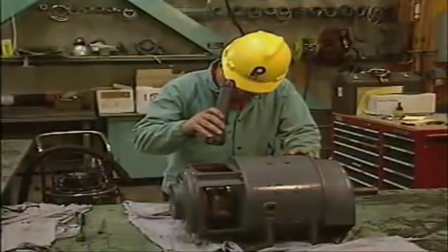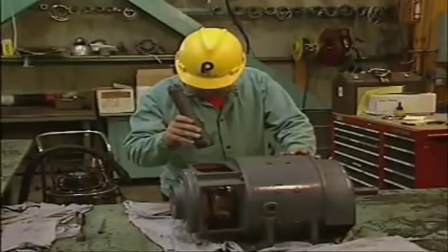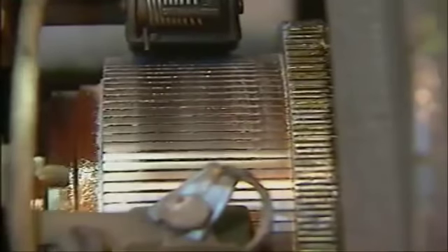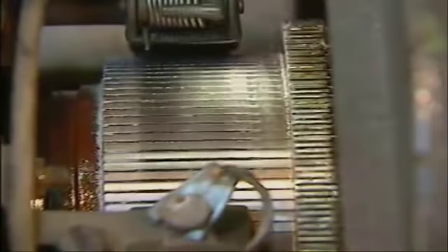Then the area between the commutator segments can be cleaned. This area is likely to collect dust, brush chips, copper flakes, and other particles. A good light makes it possible to check this area visually. The mica that is used to insulate the segments from one another ranges in color from light gray to white when it is clean. A soft brush and a vacuum hose are good tools to use to remove any particles